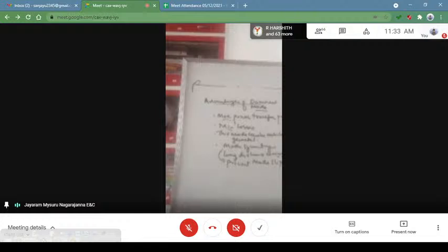So with regard to these three or four important points, we say that TE10 is the dominant mode in a rectangular waveguide. Similarly, if you consider TM waves, TM11 is called the dominant mode in a rectangular waveguide.